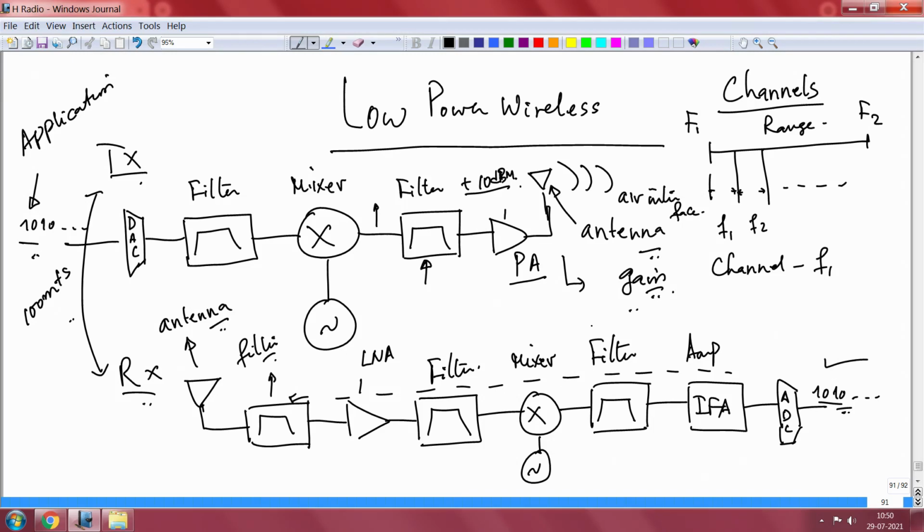The antenna will apply a certain passive gain, it will focus the energy in a particular direction perhaps, because the way the antenna is designed will give you a certain gain, and that gain will ensure that you may actually be able to transmit to 100 meters. The gain was sufficiently good to get it to 100 meters, but if you chose a different type of antenna for the same plus 10 dBm transmission power, you may have only got about 75 meters.